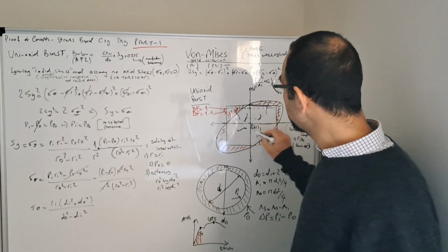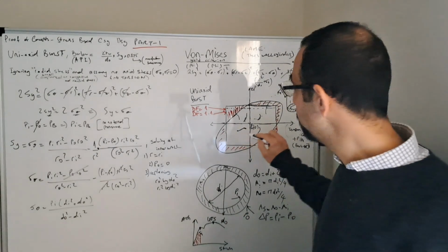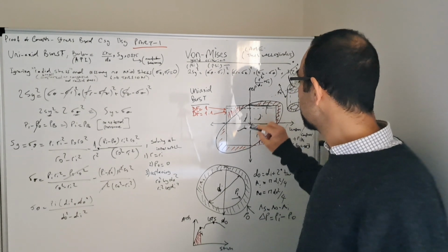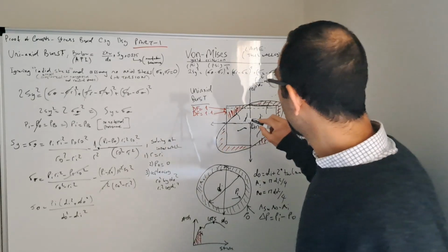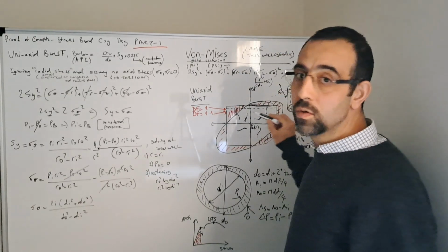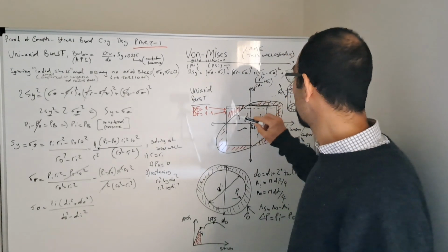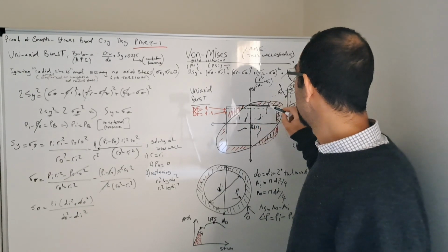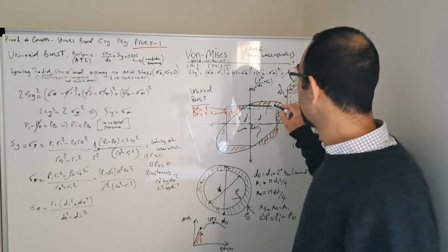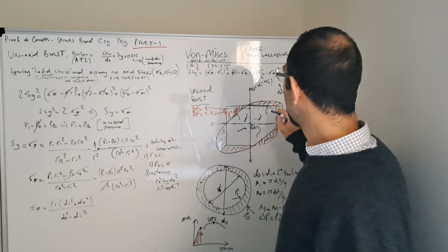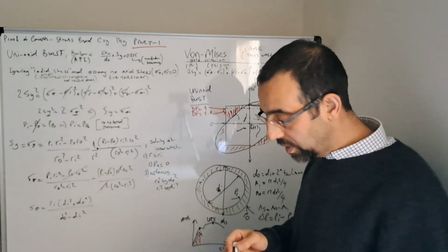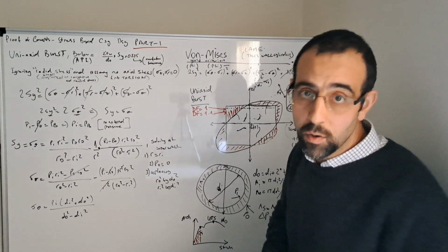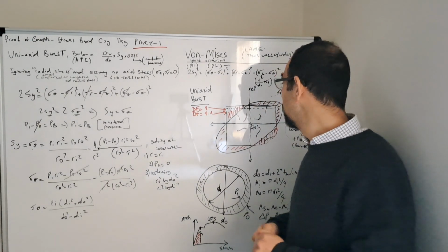And I draw some hypothetical lines here, and these hypothetical lines could extend here or they could extend there. Some companies, according to their casing design manual or standards, will let users design a load case or a casing that extends into this triaxial area where it exceeds the uniaxial limits, or some companies might not allow that. That depends on their internal guidelines.